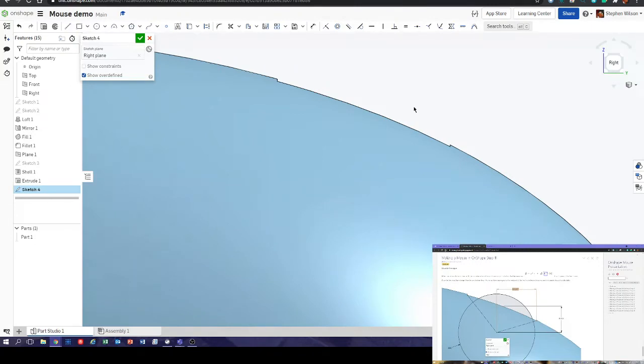All right. So what do we do? It says use the use command. So we pull in that dot there and that dot there. So let's do that. Use that point there and that point there. Okay, then we're going to do a couple of construction lines. Draw the two lines and then change them to construction lines. The vertical dimension goes to the midpoint of the line between the points, and this should already be selectable.